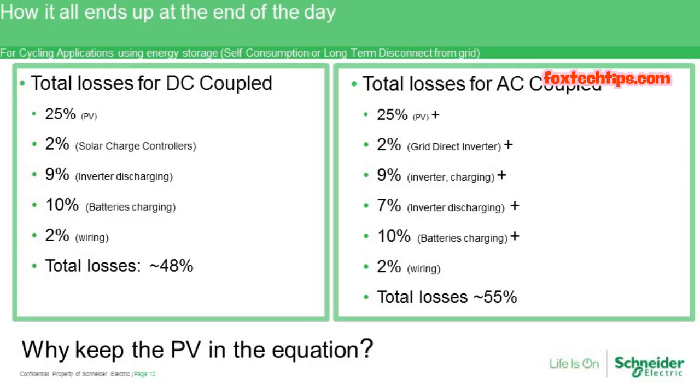Really, floating batteries maybe costs a kilowatt hour a day, maybe, especially if they're aged batteries that need a little bit of extra to keep them up at their ideal voltage. But good long-term storage batteries with an AC coupled solution is a really nice way of having that battery-based backup system ready to go, but isn't going to affect that return on investment for just a straight net metering and, say, feed-in tariff program.